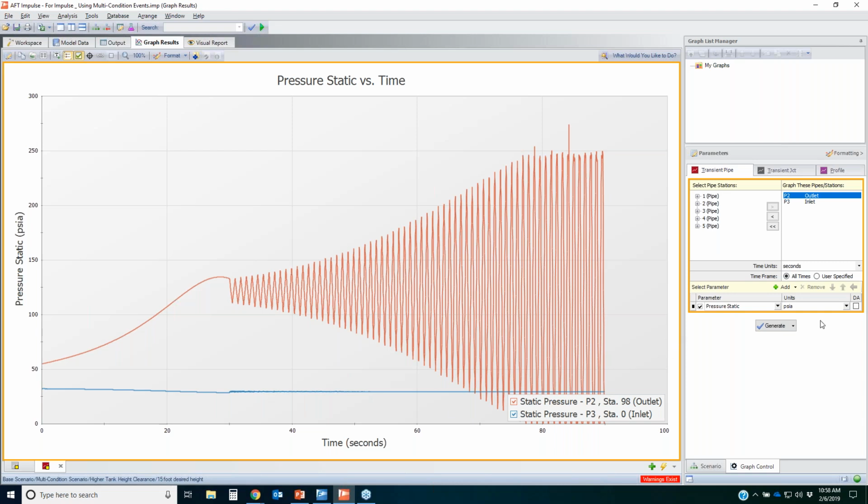So here, what we see is in 30 seconds, this is when the valve is fully closed. And so this is how high the pressure gets. So what we see here is at this particular point, the pressure actually gets up to 135 psia when the valve closes, not the deadhead pressure of 120 psia. Now, why is this oscillation happening? This is because the pump is deadheading against the closed valve.